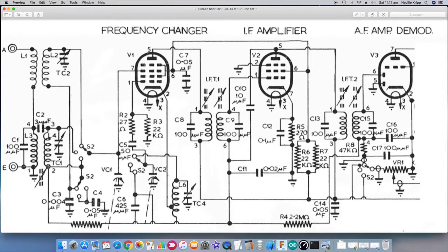Okay, so now let's take a look at a valve circuit. So here we can see the actual receiver circuit right from the antenna connection here through to the actual demodulator valve here. In the middle we have the frequency changer or the mixer and combined local oscillator. And you'll note there's ganged capacitors here, just like we've seen previously. There's quite a lot of switching and things around in this particular circuit that we don't really need to concern ourselves with. It's for switching between broadcast band and shortwave, so different tuned circuits are switched in place for the oscillator and the RF filter.